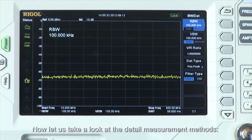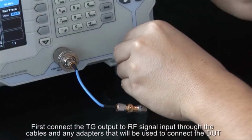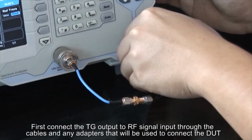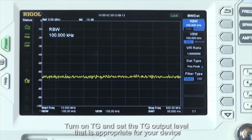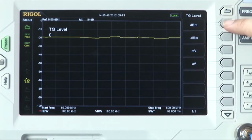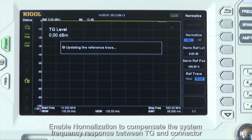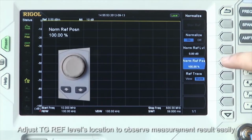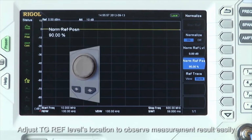Now let's take a look at the detailed measurement methods. First, connect the tracking generator output to the RF signal input through any cables and adapters that we'll be using to connect to the device under test. Turn on the tracking generator and set the TG output level that is appropriate for your device. Enable normalization to compensate the system frequency response between the tracking generator and connectors and adapters that we may be using. Adjust the tracking generator reference level location to observe the measurement and results easily.